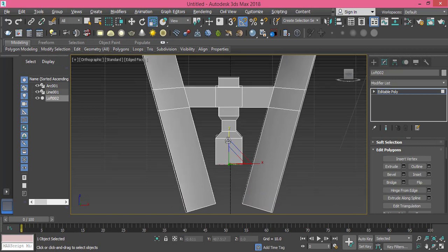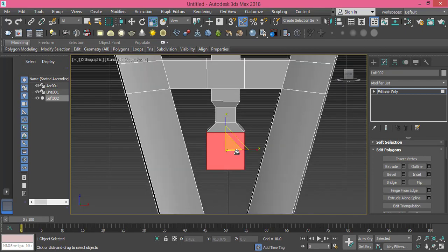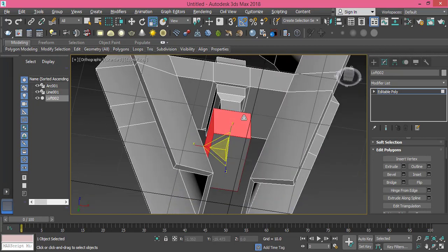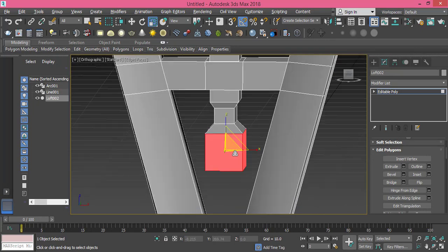That's it. Let's now do something else. Let's create an insertion on the 4 corners. So we select these 4 polygons, and let's do an insert, let's make it by polygon and with the value of 1, so we can create the hole and press OK.